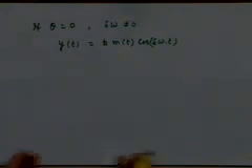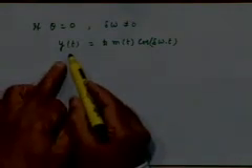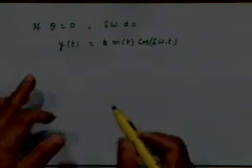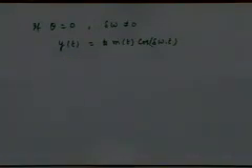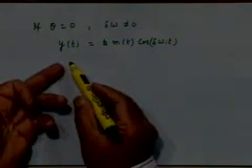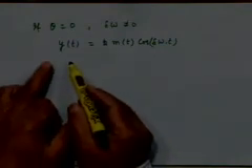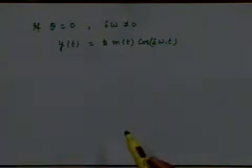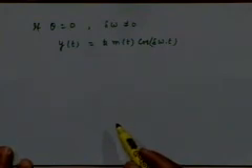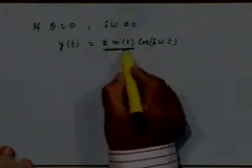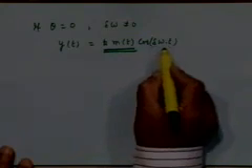But then you have to take the Fourier transform also, right? What Fourier transform? We are looking at the recovered signal y of t. Fourier transform only will tell you what is happening in the frequency domain, but this is what you are getting. After multiplying and low pass filtering, this is the output that you are getting, whereas what you wanted was k times m(t). So instead of getting what you want, you get that multiplied by something.